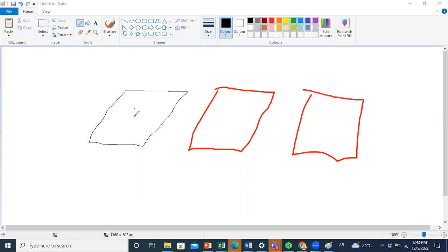Okay, so a panel is characterized by a certain area A. We know the heat flux coming from the sun. So let us call it S. Let's say, for example, it's equal to 400 watt per meter square. So we can say that the solar flux hitting the solar collector is equal to 400 watt per meter square. We have the area per channel given. Let's say, for example, the area per channel is 1.5 meters square.